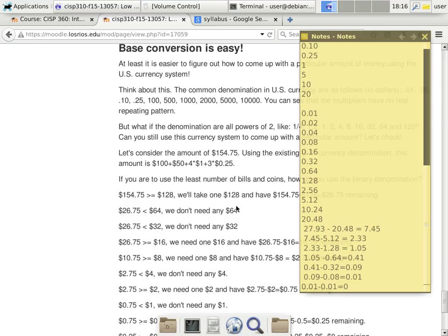Yes. Let's deal with subtraction. What is 1 minus 0? 1. What is 0 minus 0? 0. What is 1 minus 1? 0. And the only one that's tricky is 0 minus 1. But that's the same question as 0 minus 5 in base 10. You have to borrow. So 0 minus 1 is 1 with a borrow, because the next digit is going to be twice as much as this digit here. It's the same concept as borrow.